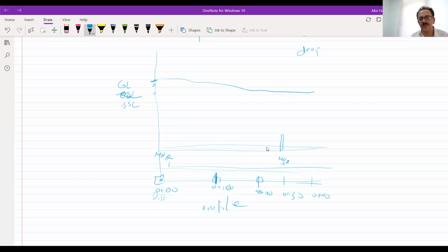Now maybe we have the ground level, you have to mention this one and the cover, and there will be a bottom surface level. Here's the bottom. So this will be manhole number 1, manhole number 2, and here you have to mention the sewer. For the sewer, you have to mention the diameter, and you have to draw this one.